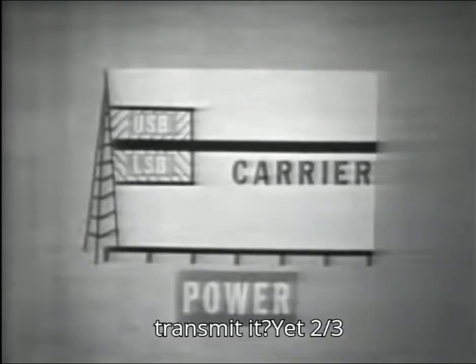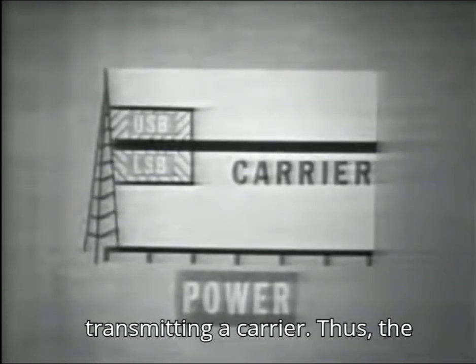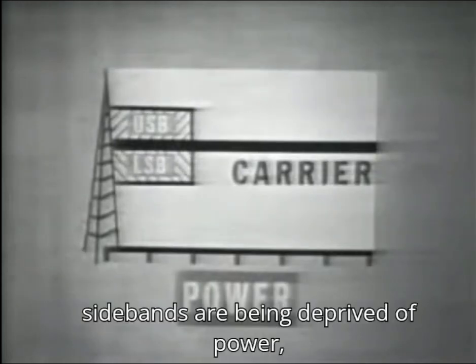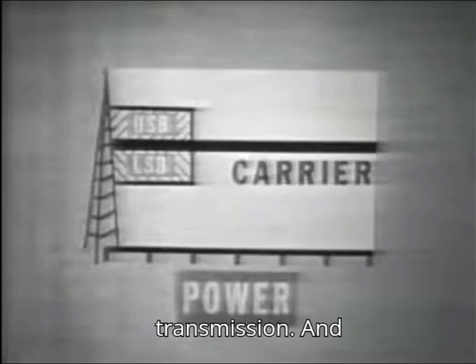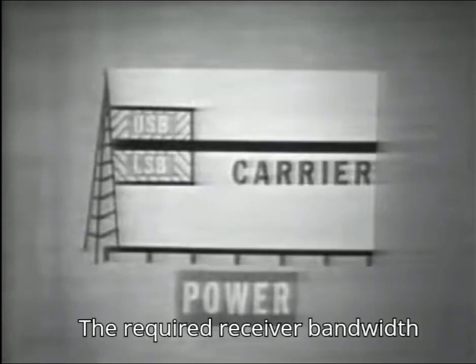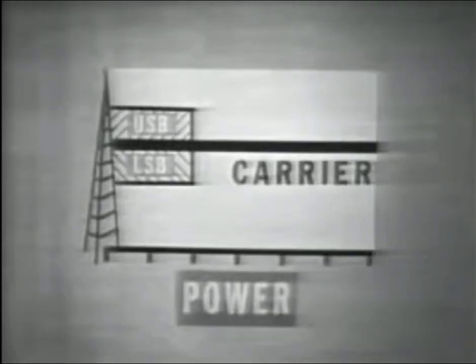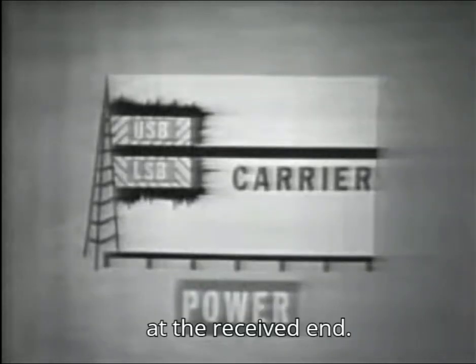So why transmit it? Yet 2/3 of the total power is wasted in transmitting the carrier. Thus, the sidebands are being deprived of power which might increase the range of transmission. And also, since we have two sidebands, the required receiver bandwidth allows in more atmospheric noise at the received end.